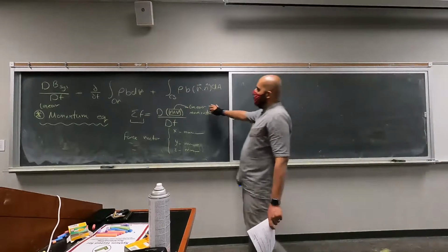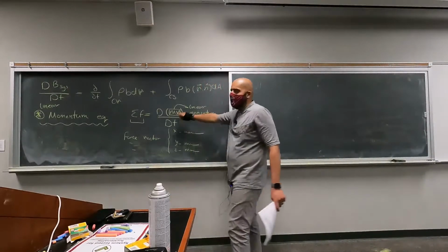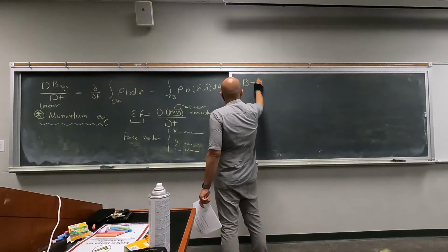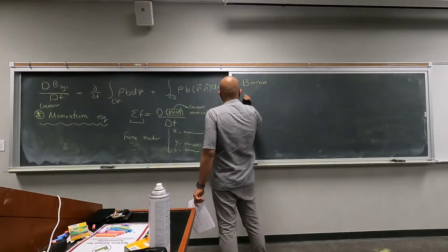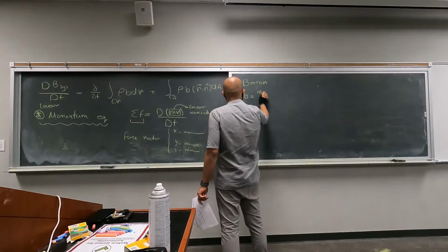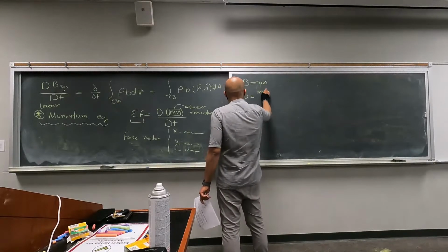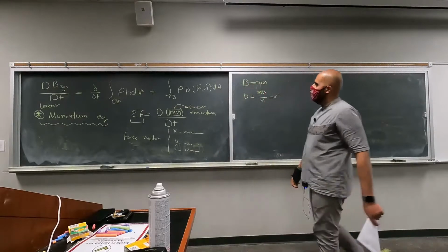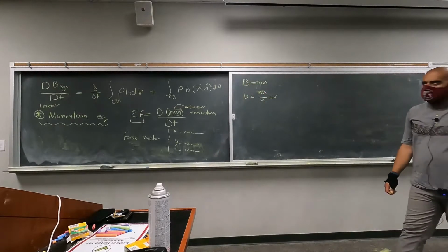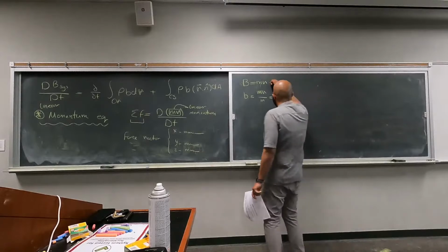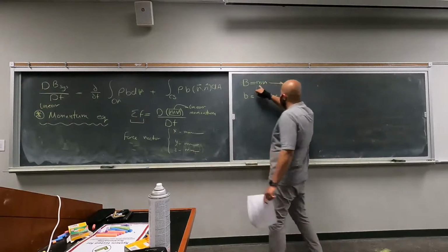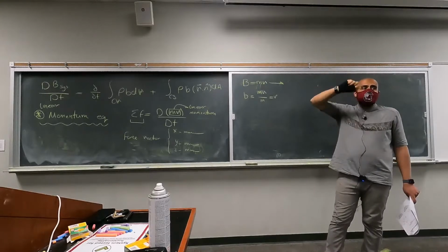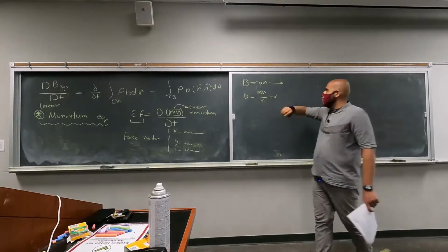apply the Reynolds transport theorem to linear momentum. The extensive property here is linear momentum, which means that your intensive property, which is linear momentum divided by m, is just velocity. Okay? And here, in calculating the linear momentum as mv, we are assuming density is uniform everywhere.